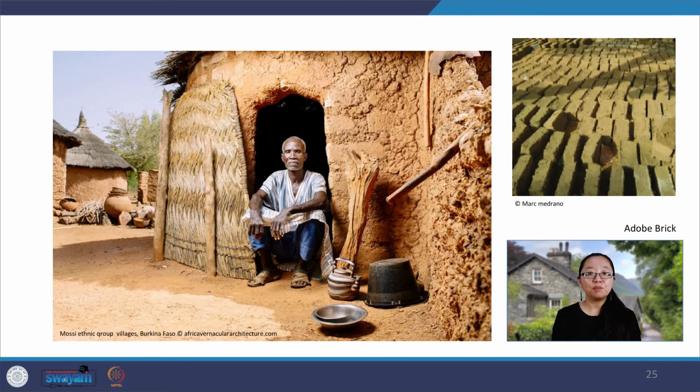In their development, more houses are built in rectangular shapes. The load-bearing walls are built with a 15 cm thick adobe brick with an interior clay coating and exterior lime coating. The adobe bricks are manually built on site. Bricks are produced in wooden molds, mixing earth, material, and water, and sometimes straw is added to limit cracks. The earth mixture is placed in molds and dried in the sun.